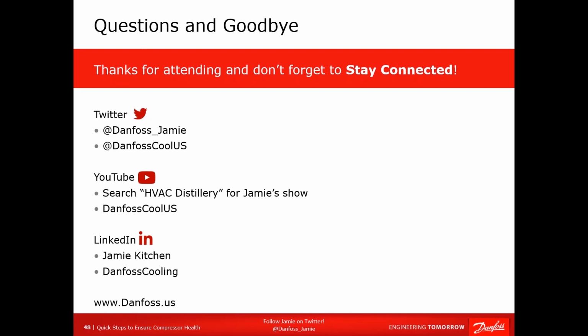Cool. Good question, by the way. Next question: is it good practice to use a starter kit for the compressor, or a start kit? I use them as a last resort because as beneficial as they are, they are also hard on the motors.